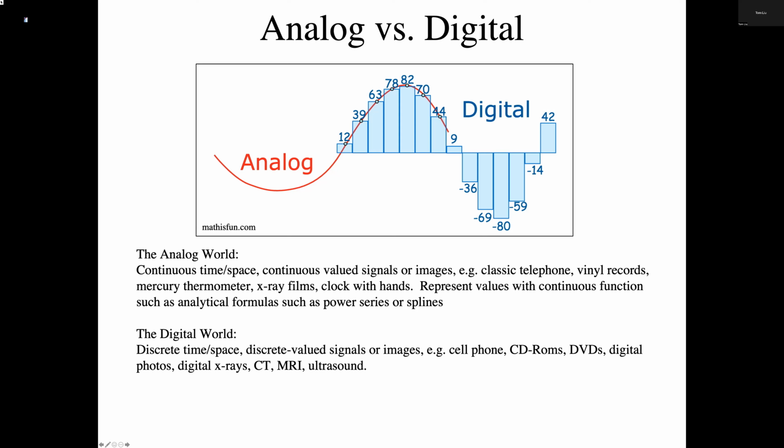And what we're going to do is digitize that signal such that we will replace a function. If I have an analytical function, I can tell you that this analog signal is, well, that's great. Oftentimes I can't, but I'm going to replace it with a finite number of values of that function sampled at some interval. This makes life easier because when I ship that function to somebody else or I put it into my computer to reconstruct, all I have to do is transmit these values. So now I've just got a list of values and that's my function. That's the representation of the function.